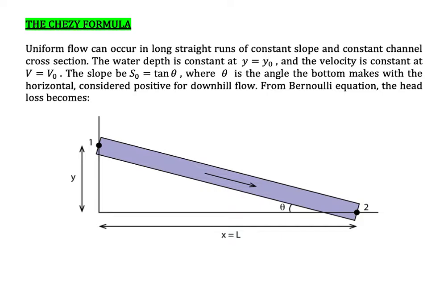We are using the hydraulic radius, and you need to know how to determine your hydraulic radius from the cross-sectional area of your open channel conduit. Today, we will see how the flow calculation is done. Before that, I would like to give you two basic equations that can be used for this type of calculation. The first one is the Chezy formula.